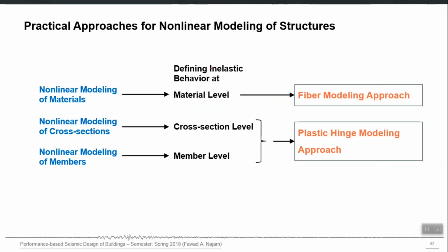So when we define the inelastic behavior at material level, this is the fiber modeling approach, right? If I have to define fiber modeling in one line, I can say that it is the type of modeling in which the material stress strain curve is directly provided as an input, which is a nonlinear stress strain curve, right?